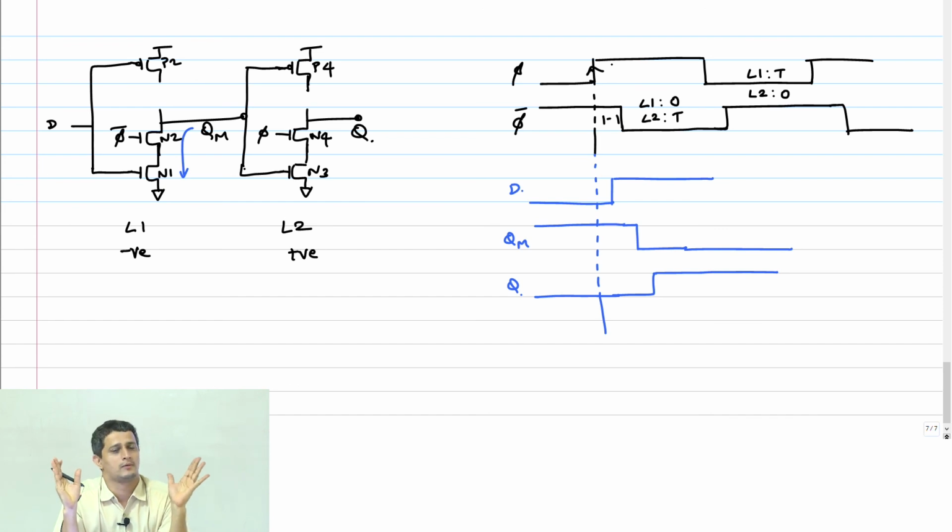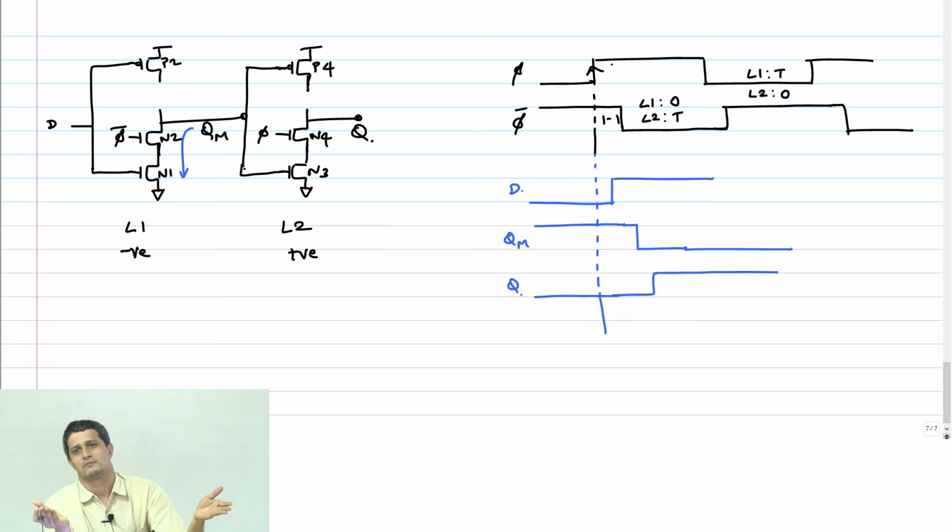The flop will work. It is a violation on the non-sampling edge that is going to ruin your circuit. And you should never have a violation on the non-sampling edge. Sampling edge, you can impose this condition. Worst case, let's say you designed it wrong, something happened. You just say, okay, my hold time is larger. It doesn't mean that the circuit is unusable.